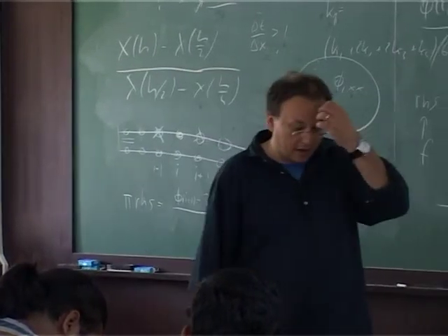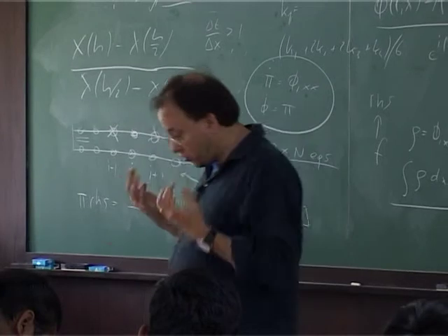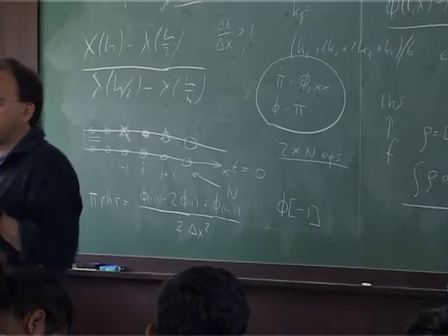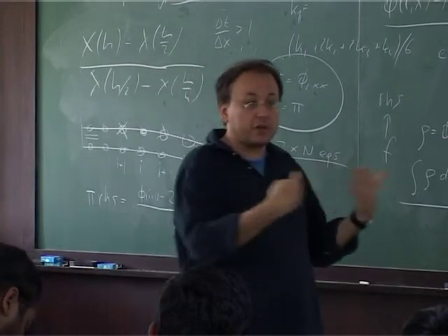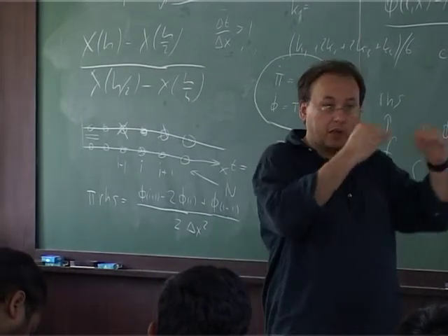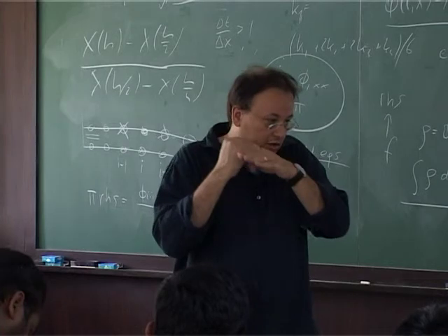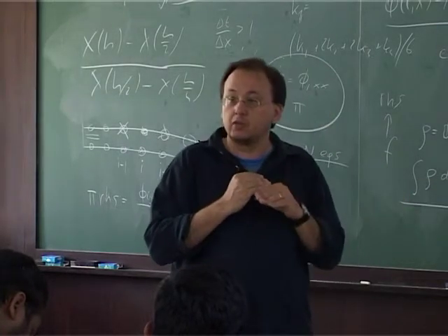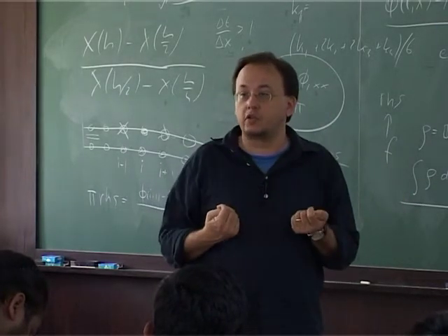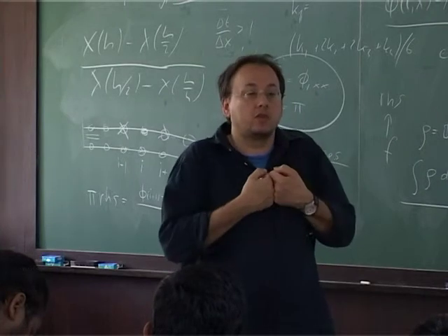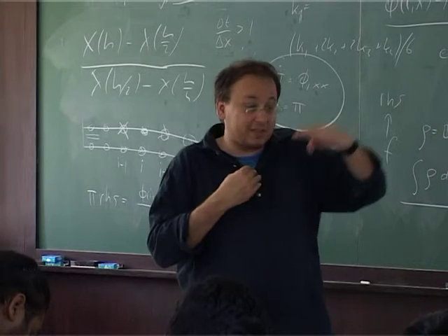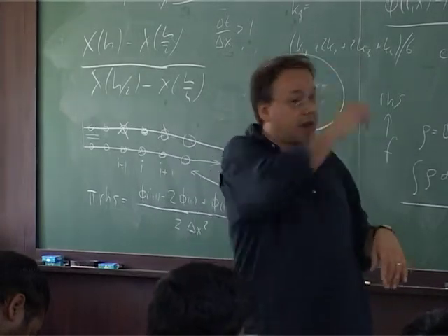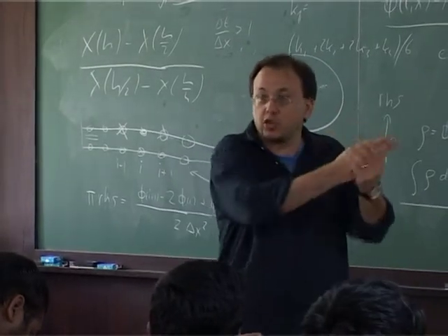The only way to find out the properties of the continuum, the true solution, is to run your code at different resolutions and look at whether you consistently approach the limit, which means carrying out the convergence test, and then estimate, not determine exactly, what this x0, the continuum solution, would be.